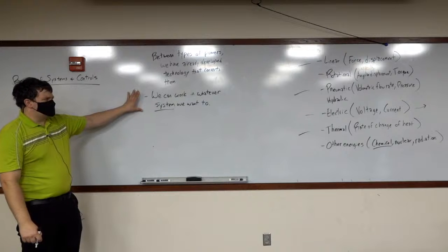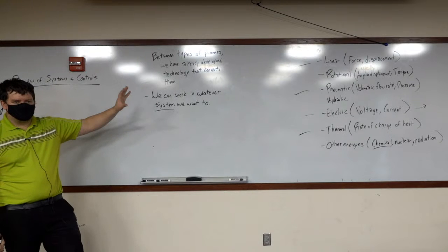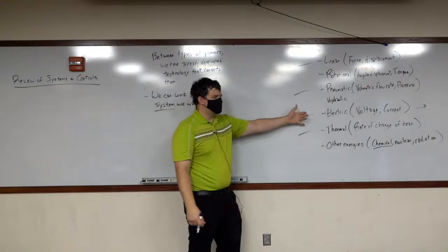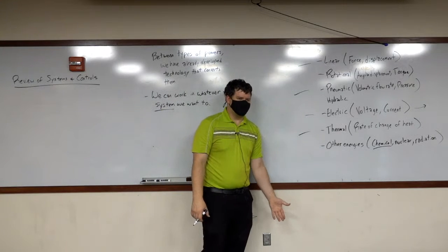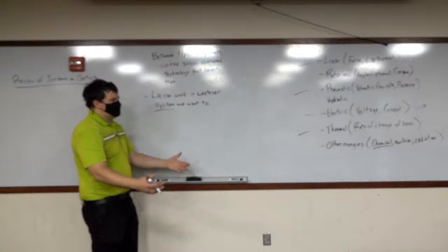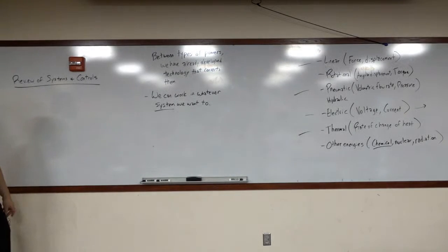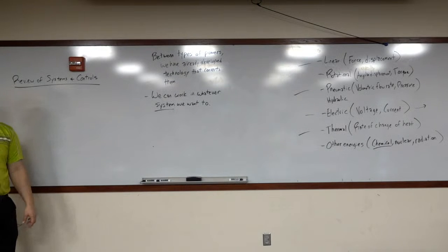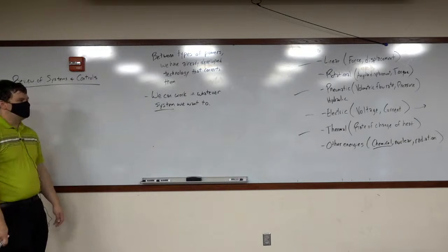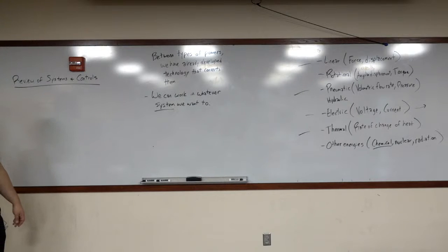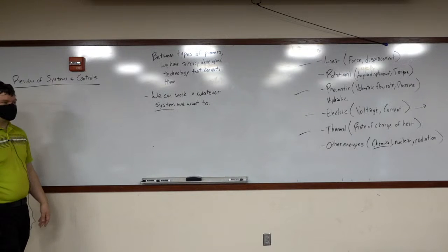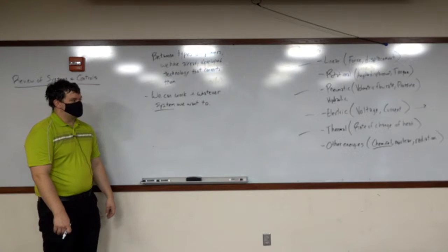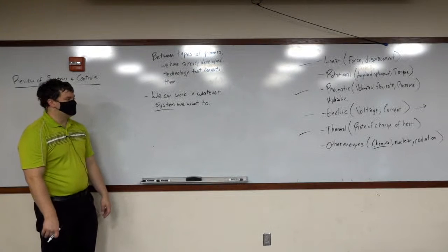It really comes down to this principle. Because we have the ability to convert between systems, you can work in an all-electric system. Now, there are benefits of working in an all-electric system as opposed to trying to work in an all-pneumatic system. The HVAC system for this building is all pneumatic, and it is the worst ever. I don't know who thought that was a good idea 20 years ago, but they don't do that. No one does that, okay? Electrically actuated vents are just more effective, more reliable, but nope, they wanted pneumatically actuated vents.